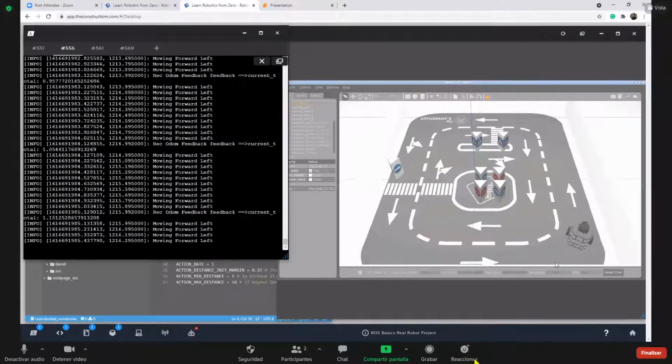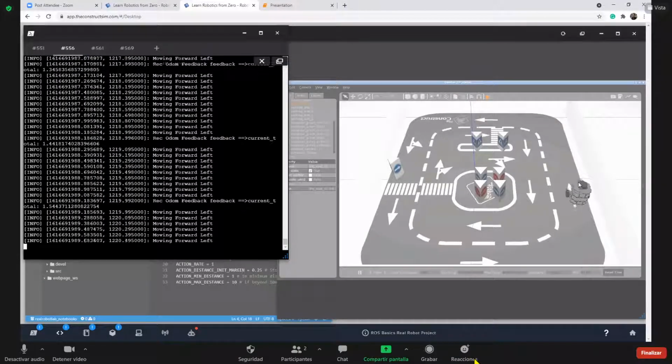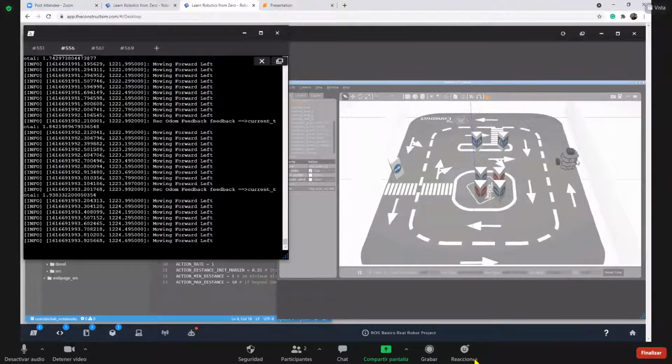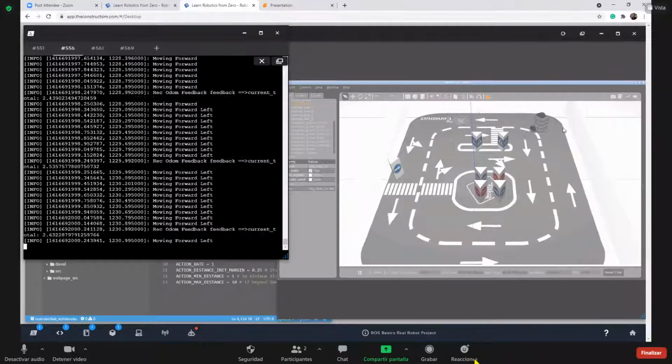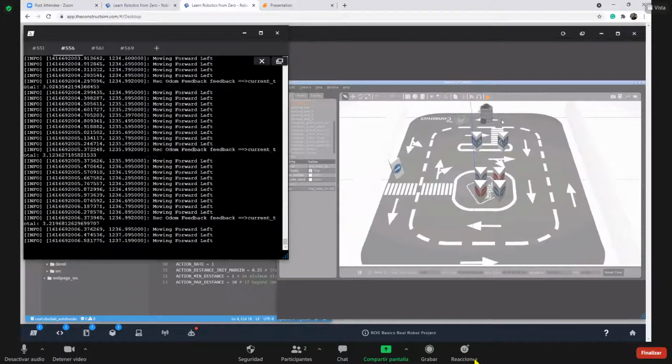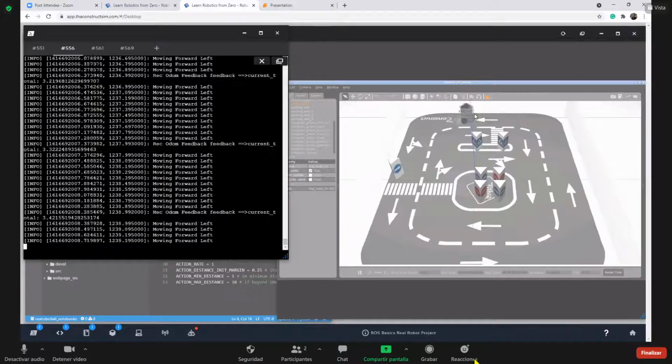That is the specification. When it sees a wall, it means that the reading of the sensor is smaller than 0.5 meter. It will start rotating to avoid that wall, so it will move away from this wall. And because it is a rectangle here, we expect it to follow a rectangle path. And as you can see here, it turned to the opposite side.